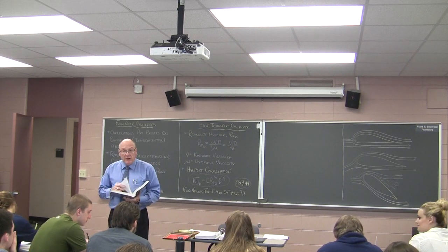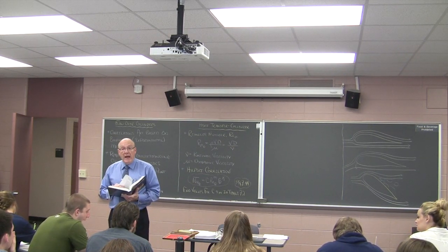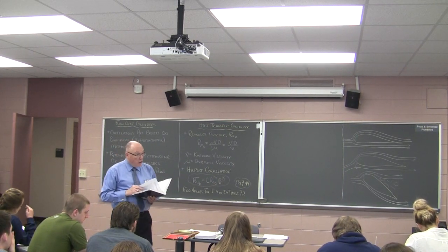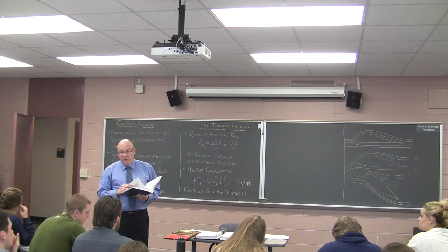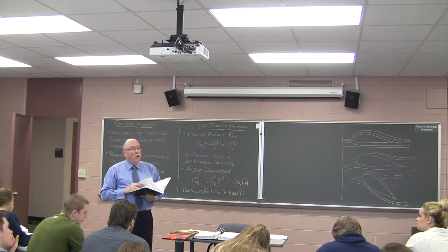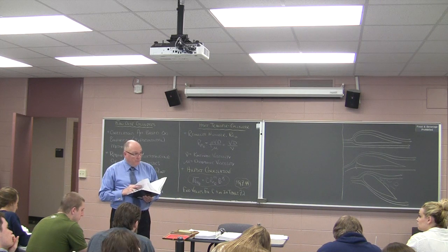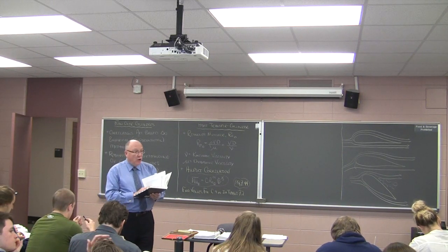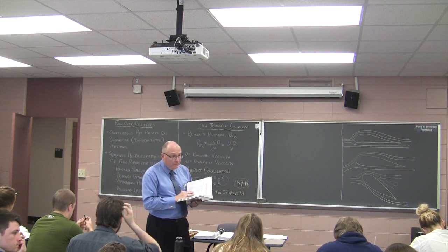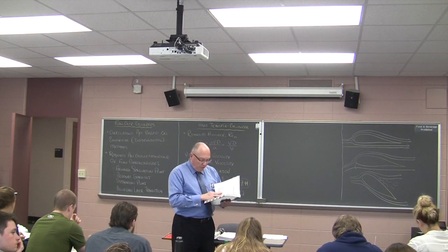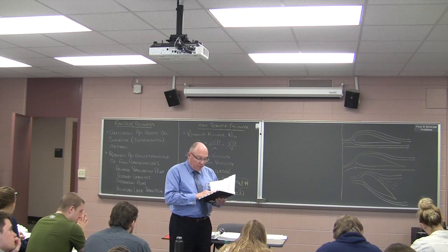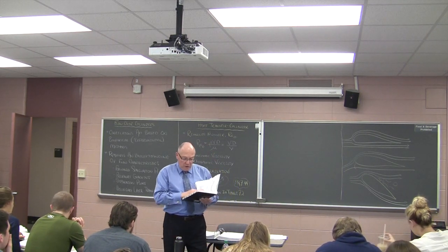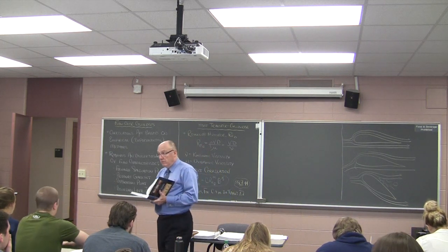And now let's take a look here at the values. This is an equation which produces an average Nusselt number. That is not a localized value at some point around the cylinder, but an average value around the entire cylinder in cross flow. Okay, so it's very useful in that sense. You'll see that it's based on T_f, the film temperature. You'll see that it works for a very large range of Reynolds numbers from 0.4 up to 400,000.